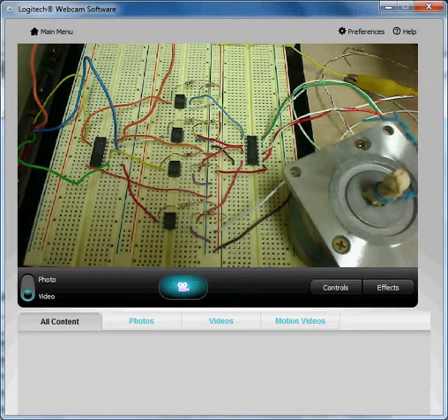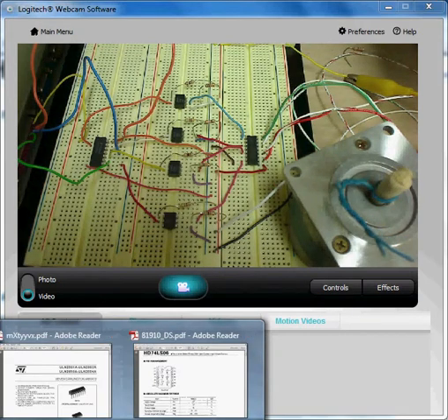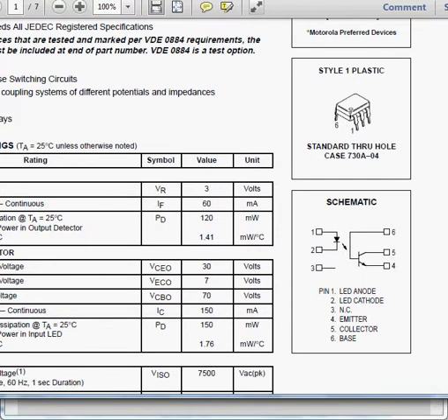After the sequence code passes through the hex inverter, it will pass through the 4N26. Last time we already used the 4N26 to build the driver. Here, instead of 1, we need 4 of them, since we are going to drive 4 coils. The 4N26 is the opto isolator transistor.